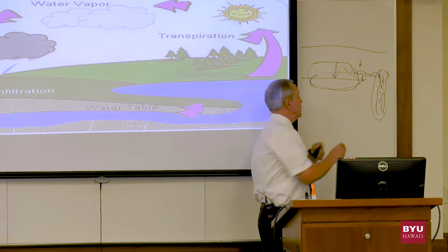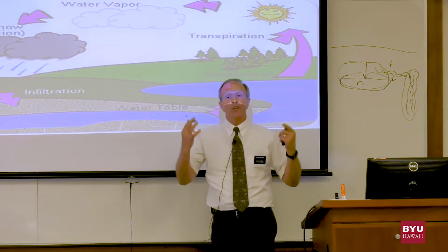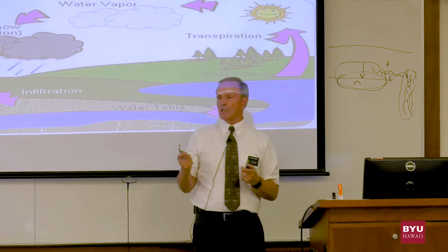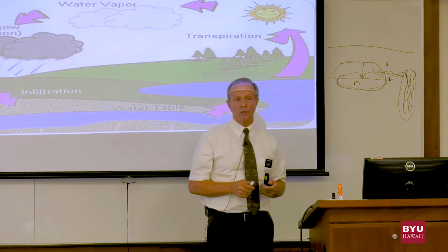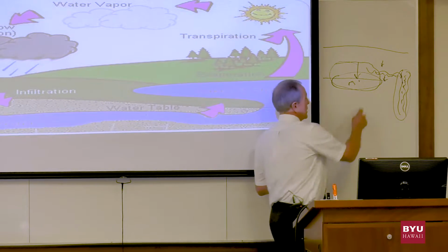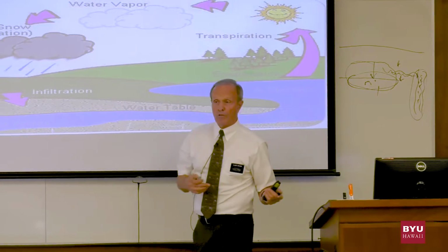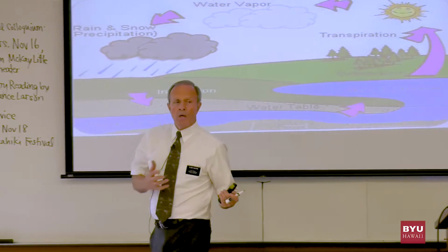This little aquifer, again, your aquifer sitting here, does not have, quote, the recharge. What's a recharge? That's the amount of water coming into your formation. So if you don't have enough water coming into your formation and you're extracting at a certain rate, then pretty soon you're going to dry up that aquifer and it's no longer available for use.